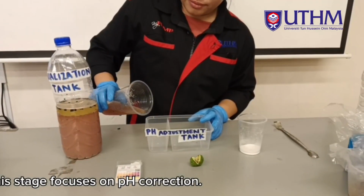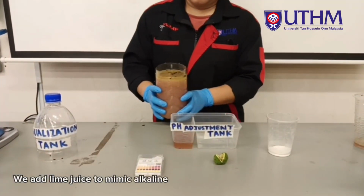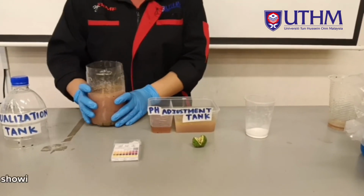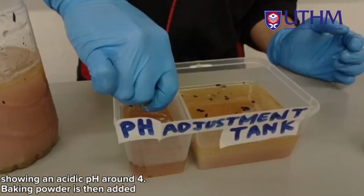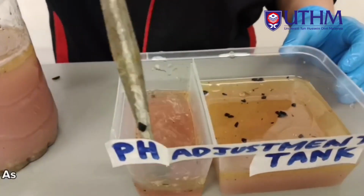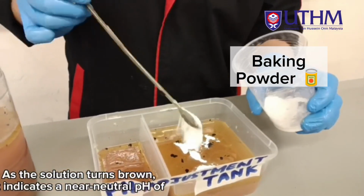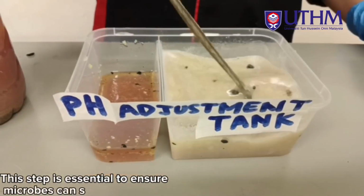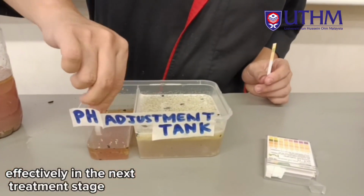This stage focuses on pH correction. We add lime juice to mimic alkaline dosing, causing the red cabbage indicator to turn pink, showing an acidic pH around 4. Baking powder is then added gradually. As the solution turns brown, it indicates a near neutral pH of approximately 7. This step is essential to ensure microbes can survive and function effectively in the next treatment stage.